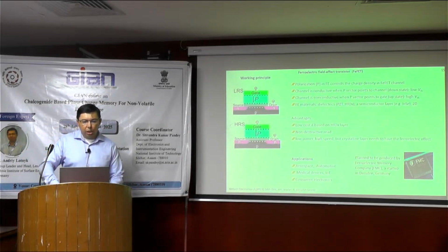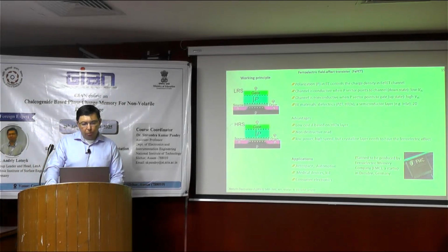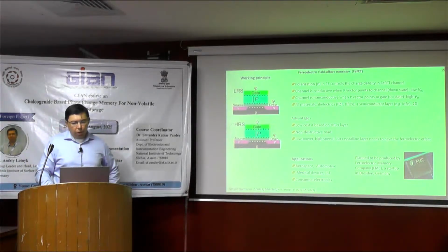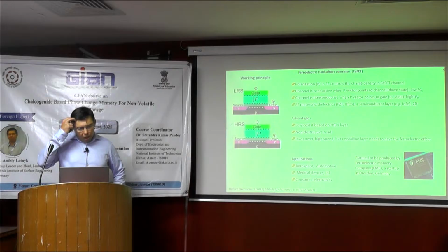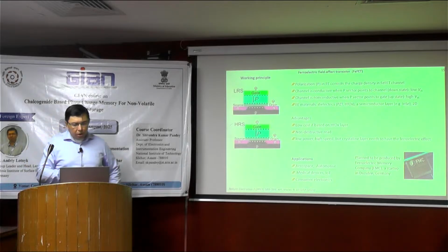Advantages: it's low cost if based on hafnium oxide, but high cost if based on PZT. It's non-volatile, low power, high speed, but in all cases you need crystalline layers to have the ferroelectric effect. And applications are aerospace, automotive, medical devices, IoT, and consumer electronics.